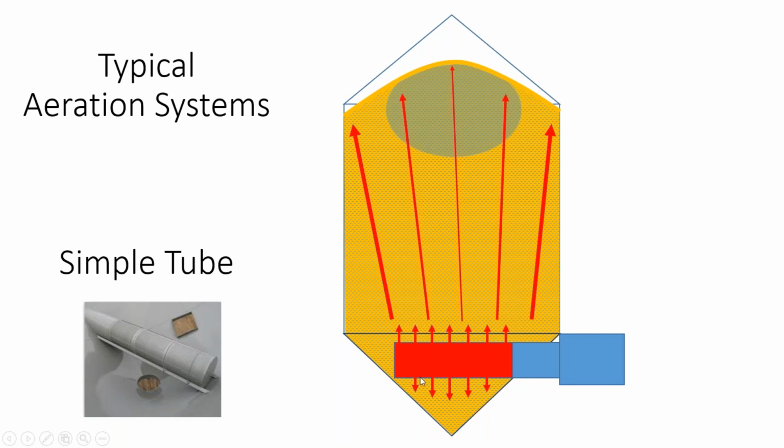And if you look at the worst case scenario, or the air that is being pushed out the bottom of that aeration tube, you can see that air has to go down, turn around, and come back up. And assuming this is 24 inches, that air has to probably go close to 3 feet before it gets to the top of this grain tube. So you can see there's a percentage of the air here that has a lot tougher path to take.